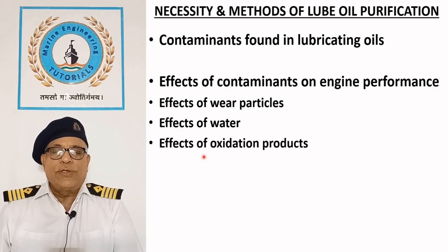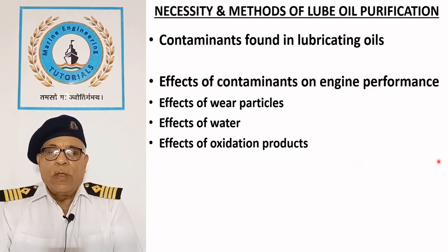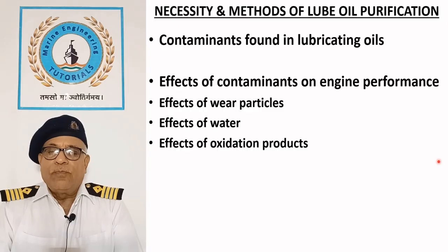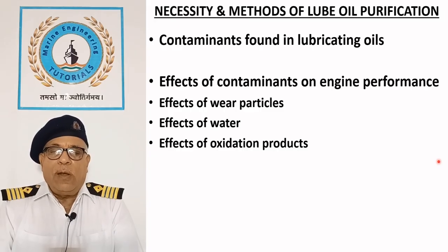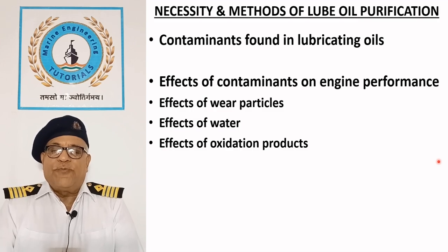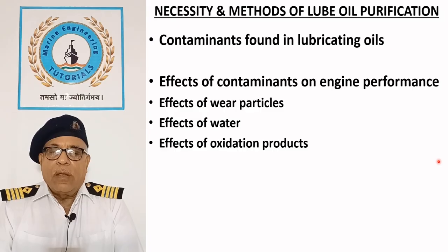Effects of oxidation products. Oxidation of lubricating oil results in formation of sludge and varnish, which are responsible for clogging of filters and reducing the heat transfer. Oxidation increases oil viscosity, which reduces film strength, load bearing capacity, oil flow, and heat transfer, which is responsible for increased friction and wear leading to possible engine seizure.